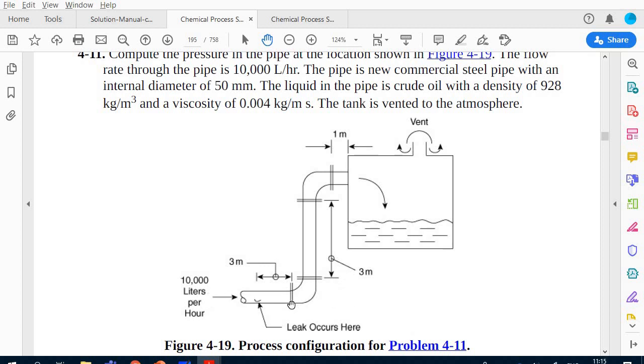So we need the Reynolds number. We need the roughness factor of the steel, and we know the internal diameter. So E over D with the Reynolds number, we can get f. Of course, we're going to get the Fanning factor, just part of flowing through the pipe, but we need also the friction factor of 2 elbows and the entrance and the exit. We sum up all of these K's so that we substitute to find F. So now that is for F. What about delta P? In this case, we need to calculate delta P.